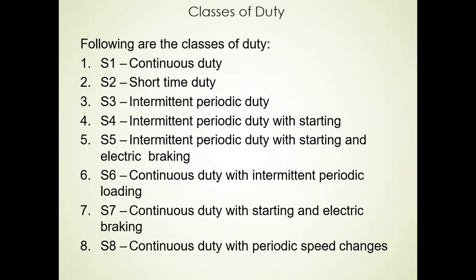According to IEC, IS and BS standards of specification, the standard duty classes are designated as S1, S2 up to S8 as described. The standard operating conditions are designated by the letters N, R, D, F, V, like that. The rating classification based on operating duty is designated like MCR, ECR, DTR.